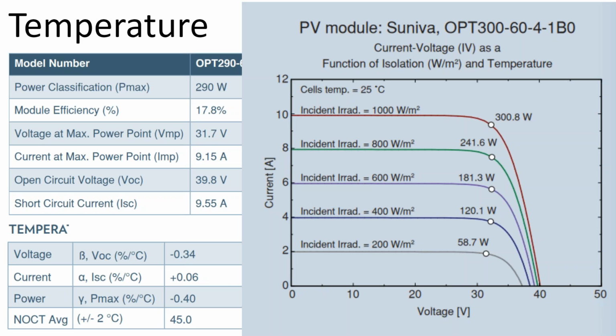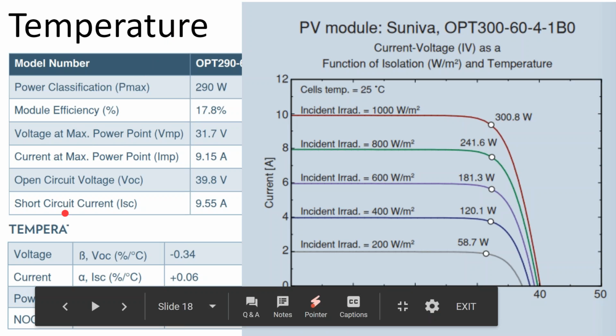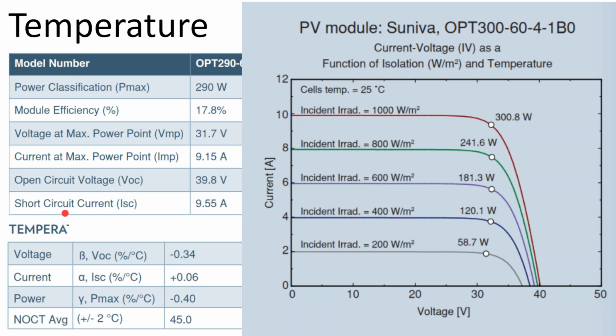Now, we can calculate the impact. In fact, PVwatts does calculate that. They make some assumptions. What the commercial data will do is they'll use the actual solar panel that you're designing the system with to perform the calculation. PVwatts gives you a couple of values that you can switch between. But what we see on the solar panel is what's called temperature coefficients of voltage, current, and power.